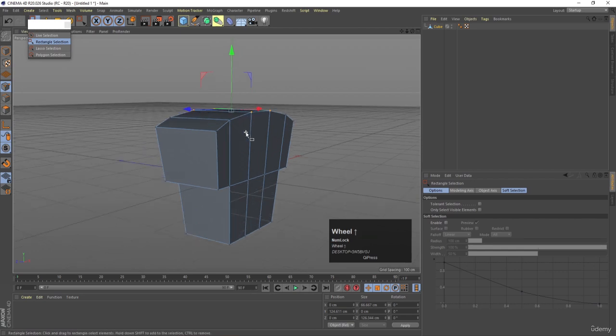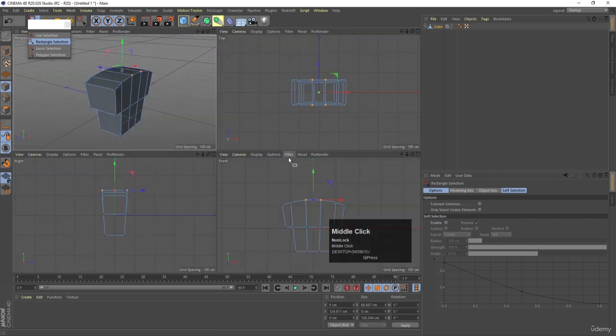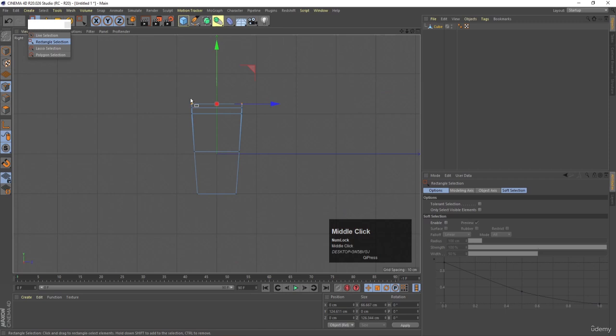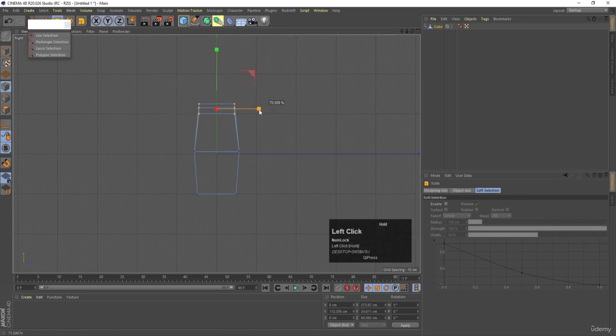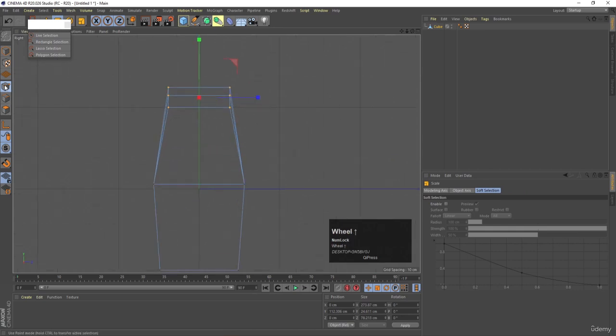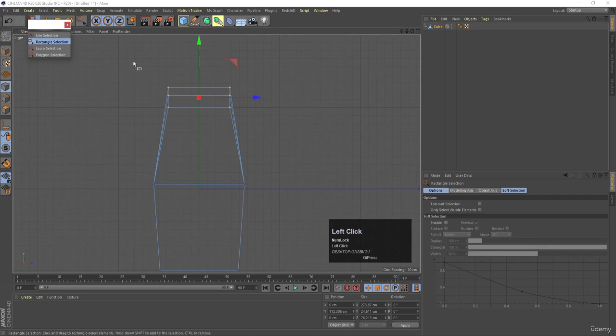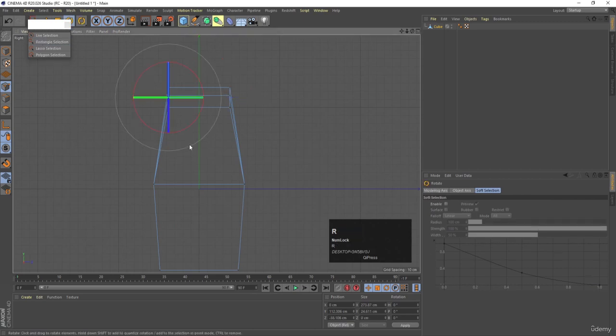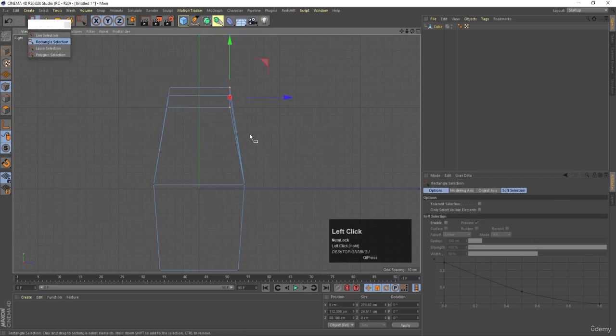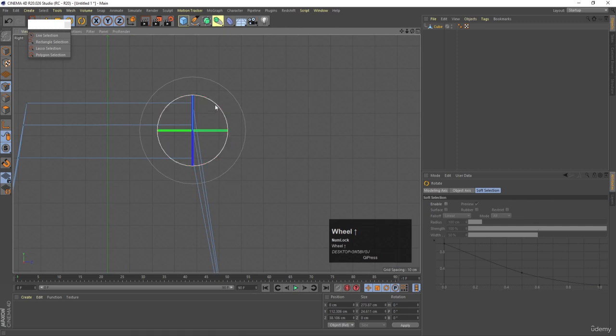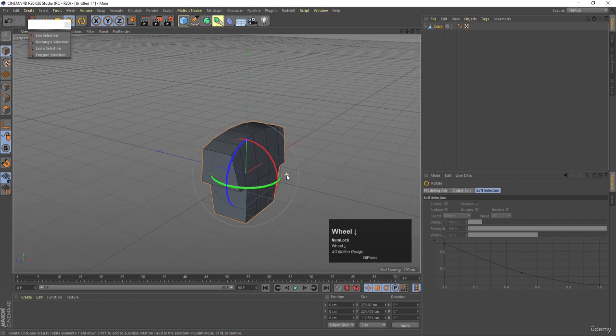Now after that, what we need over here, let's go to the right view and we will select all these points over here. Let's press T for scaling and let's bring them over here like this. Okay, now after that I'll select these points. I'll select this rectangle selection tool and I'll select those points. I'll press R on my keyboard and I'll rotate them like this, like so. I'll get this kind of structure. Then I'll select those points, I'll press R and I'll rotate it like this. Okay, so we will get this kind of structure over here.